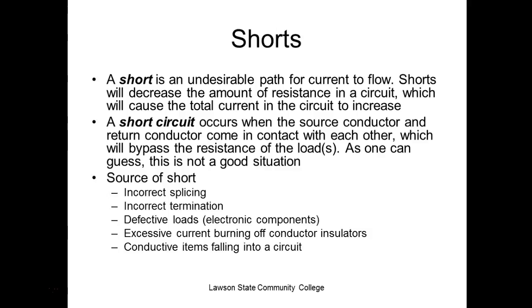Now, a short circuit is when, for some reason, the two conductors that apply power to my circuit are connected. We understand that every electrical device has to have at least two wires connected to it, right? So when we send power through a circuit, if we lose one of those wires, we call that an open circuit, or an open. But if we connect those two wires that come from our power source, in DC we call them the source conductor and the return conductor, this is called a short circuit.